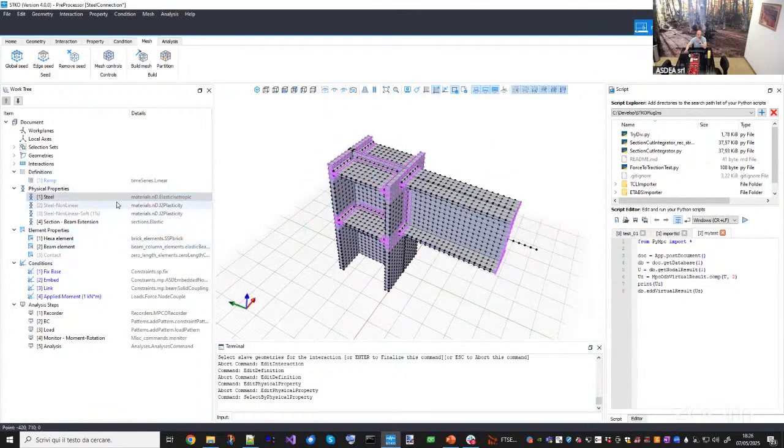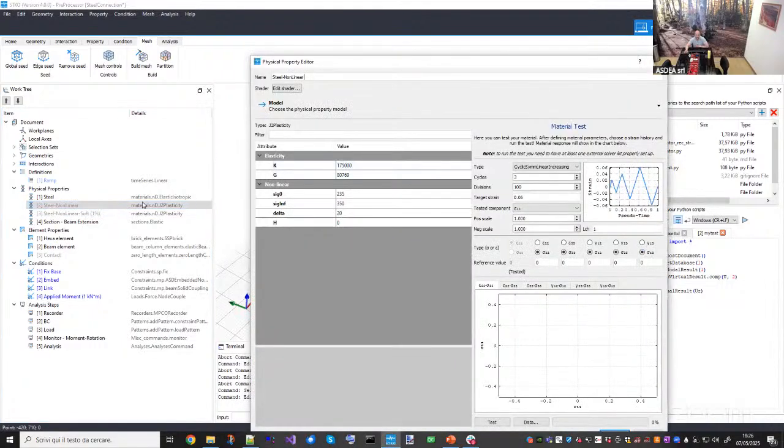Then you will find 2 other materials for steel. Now, as you know, steel requires the most standard constitutive model for plasticity, which is the J2 plasticity or the von Mises plasticity. The second one, called steel nonlinear, is exactly the same as the steel here. The only difference is that in the elasticity part, instead of asking for Young modulus and Poisson ratio, it asks for the bulk modulus and the shear modulus, but there are simple equations to obtain them. And of course, you need to assign some nonlinear parameters, okay?